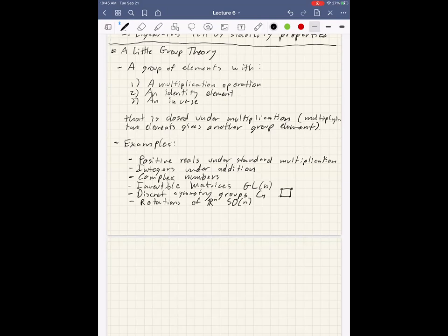It's just a set of particular matrices that's closed, where if I multiply any 2 of them, I get another one. Turns out pretty much all the groups we care about are just particular classes of matrices where they form a closed set. So they're in general subgroups of this GLn, pretty much all of them. Another one that's really good are rigid body transformations, which we're going to talk about too. Anyone know what that one's called? SE(3), for special Euclidean group. And this is translation and rotation together, right?